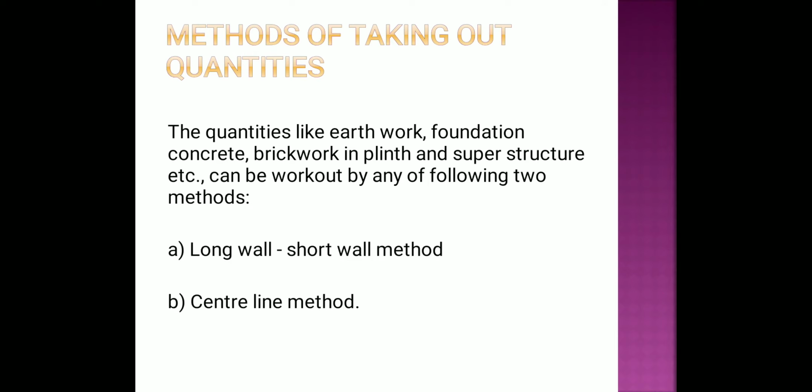How do we take out the quantities? What are the methods used for taking out the quantities? The quantities like earthwork, foundation concrete, brickwork and plinth, and superstructure can be worked out by following two methods: long wall, short wall method, and centerline method.